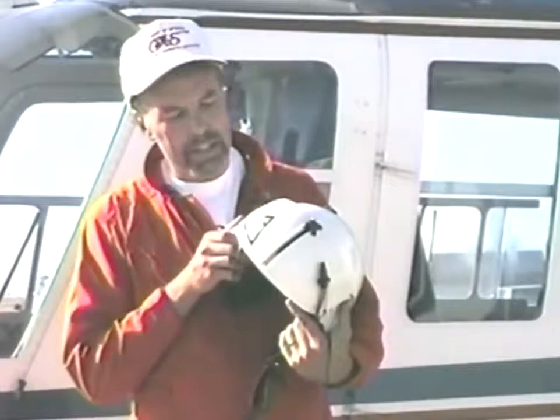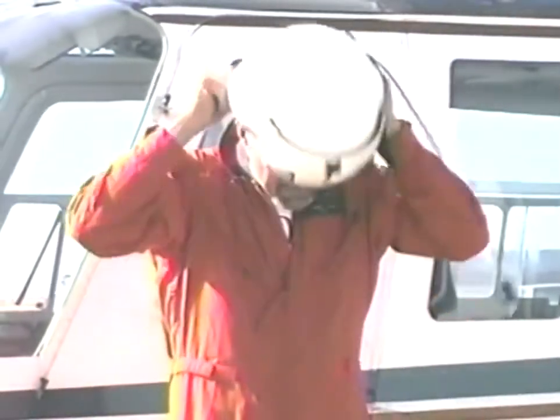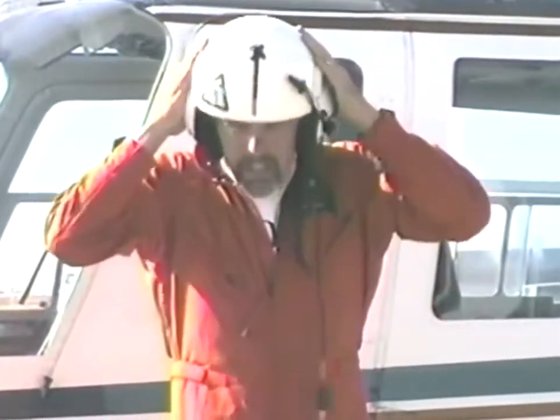Your instructor is going to demonstrate to you the proper wearing and fit of the flight helmet, but I'd like to share with you a couple of things that I consider to be very important. One thing you need to remember, when you put the helmet on, fasten the chin strap. Adjust it snug. It's useless without it. The helmet won't stay on your head in the event of a crash. So the helmet's on and it's fastened snug.